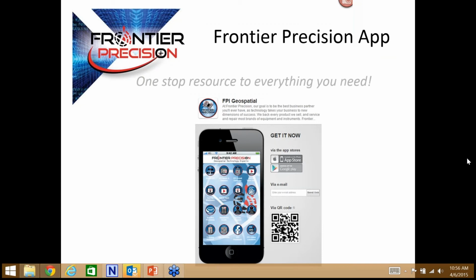Other users found VRS may lose fix easier, faster than if using an RTK base station. And it's much the same, but we're just not paying attention to it, and Jay answered this as well. It's likely related to cellular service. One thing to keep in mind is that the voice and the data services are different. As an example, if your phone says it has 3 bars of voice, you may not have that same data service. Keep that in mind.